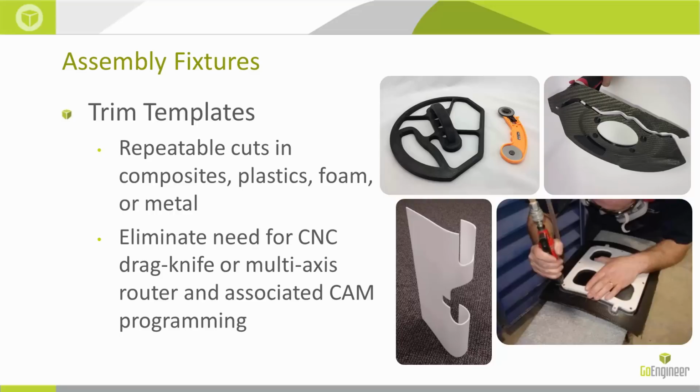So looking at a couple of examples here, the one in the top left is used to cut some carbon fiber ply. It's just a simple 2D cut. That would be a drag knife application. But you can see that jig or fixture, that's very ergonomically shaped. Looks like it would be very lightweight. Especially something to keep in mind here is that most of these examples are printed with FDM technology. And with FDM, we can control the density of the prints. So something like that wouldn't even have to be solid. It could be quite sparse, very lightweight.